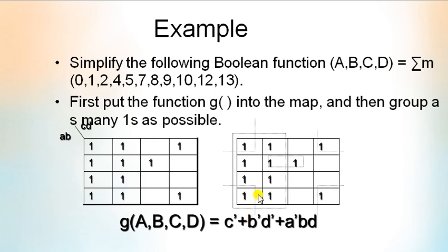For solving the Kmap, we will put the variables for 0 as the complemented one, and for 1 the uncomplemented variables in the result as a Boolean expression, and also check the states of the variables, whether it is different or same.